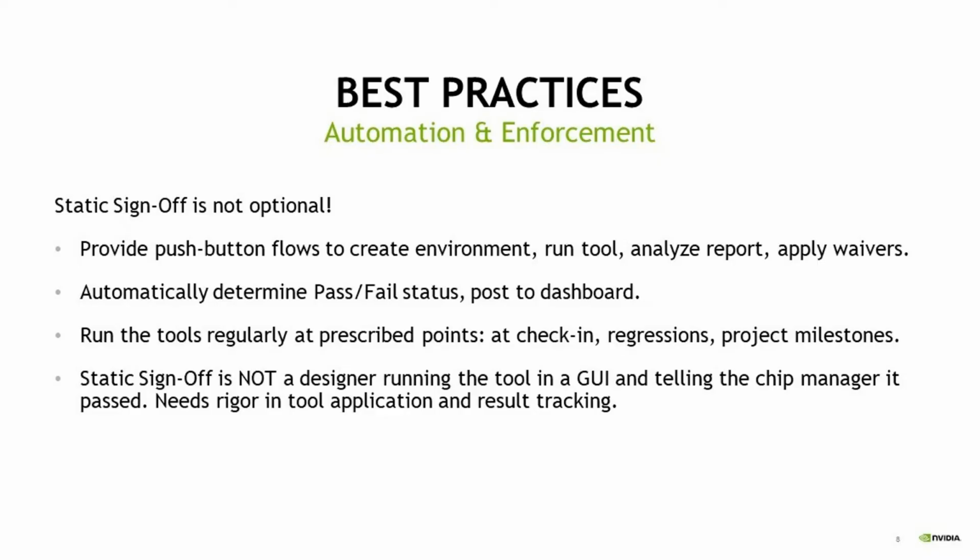So to apply these tools, some of the best practices that we recommend, much as Hamid mentioned, involve a lot of emphasis on automation. We want to make it very easy for our designers to run this in a push-button manner, and we want the grading of the results to be clearly go or no-go, and we post it to a dashboard so that the chip management and the design teams can see whether they're clean as far as static sign-off.